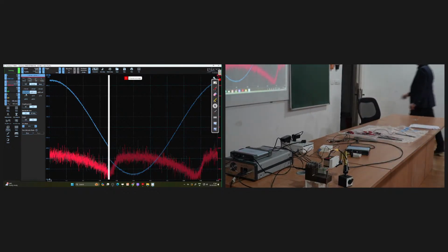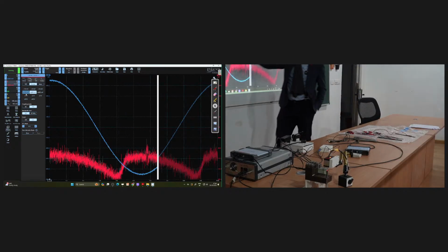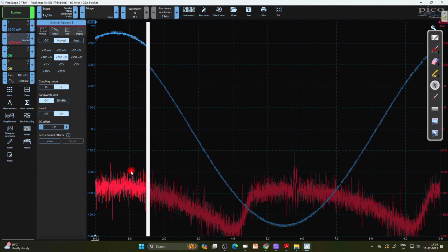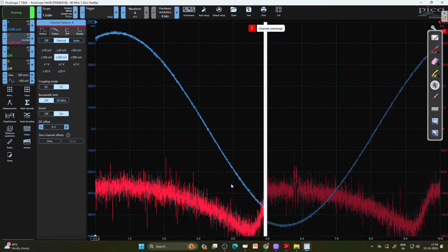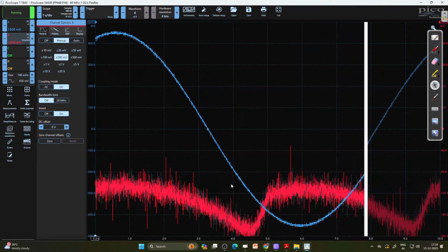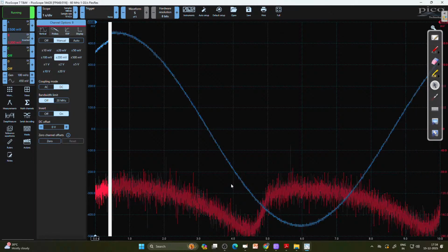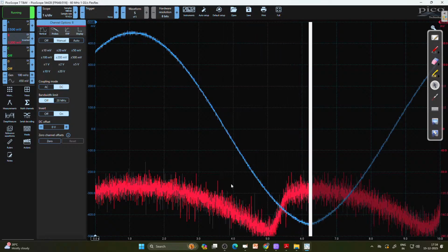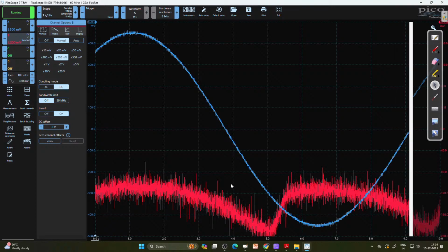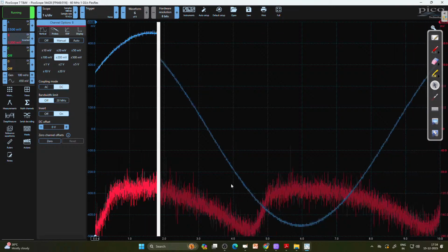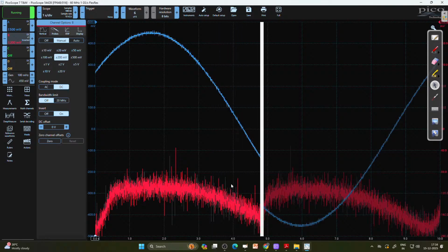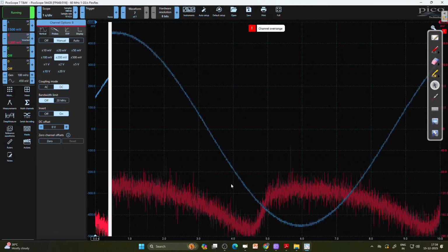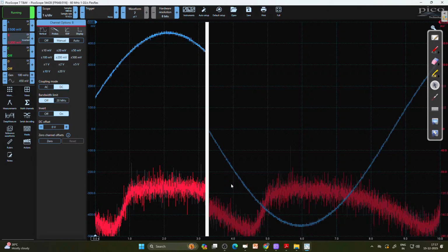And now what you can see, first of all, is that always when the, thank you, with the point, right? Yeah. Okay, so I think I use my hand. So always when we pass 0, shortly after, like here, before we reach the maximum of the blue curve, the polarization changes. So the elongation becomes maximum, and then it changes. And then again, here we go above 0, and shortly after above 0, the elongation abruptly changes. So this is when we reach coercive field strength and when it shifts around.